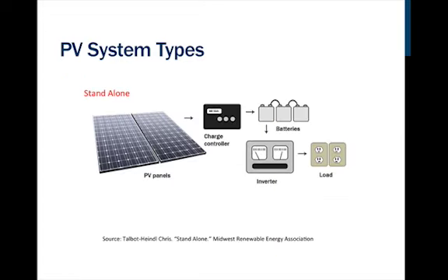Very reliable systems. A standalone system is a different kind of system, and we see more and more of these types of systems out there, but not in the form I'm going to tell you about first. So this is a home that's going to be powered solely by PV. We aren't going to have any interconnection with the utility. So our array size is going to be larger because we're going to size it for when we have the least amount of resource, which would be the winter time. Generally, it's going to be running at low voltage as well.